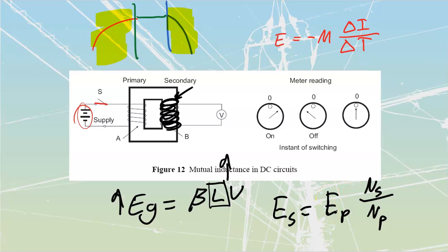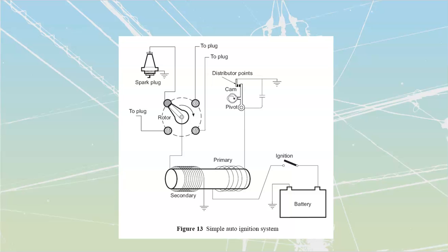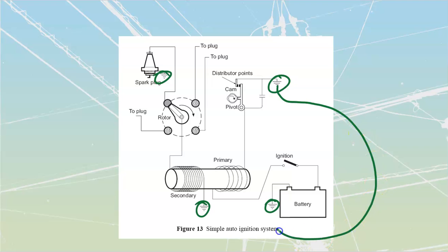And what they show us is a DC system where we are going to create ignition. One of the useful points that arcs can do for us is to create this ignition, where we have current that is fed into one side and it gets opened and closed. If I take a look at this, a couple of things I want to note. They show ground off of these. Anytime that they show ground, you can just physically draw a line from component to component to show that those two are connected. So I'm just going to draw that right there, like that.